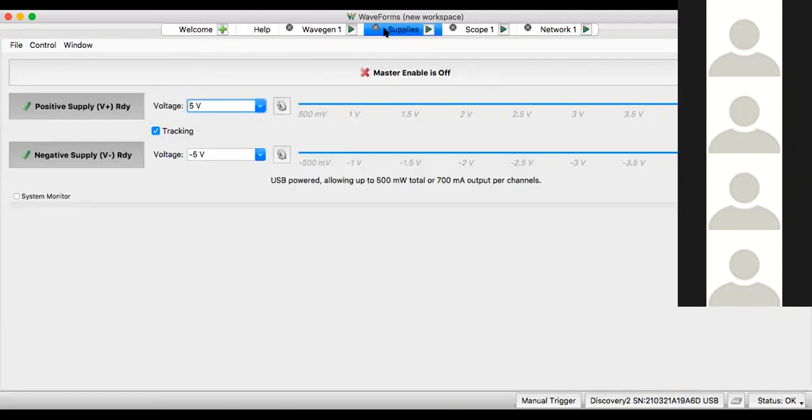First I need to turn on the power supply. That will be my power supply. The power supply will be positive and negative 5. This op-amp can work with positive 5 and 0. That means a single power supply. It also works with a dual power supply, that means positive and negative 5. That's what our setup is. So we have positive 5 power, we have negative 5 power, goes to the op-amp.